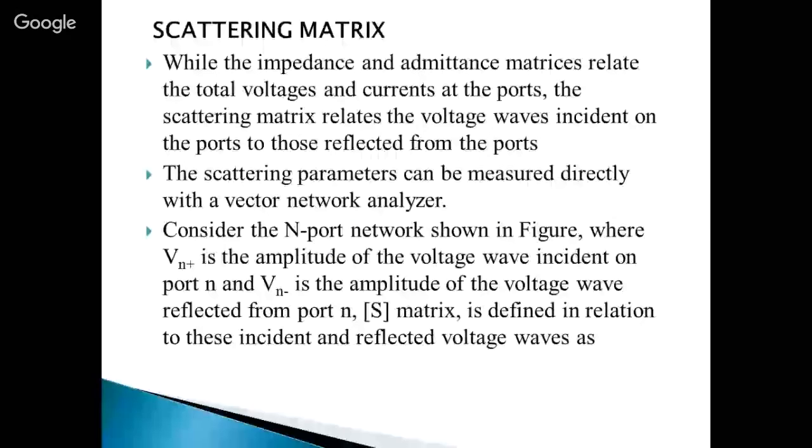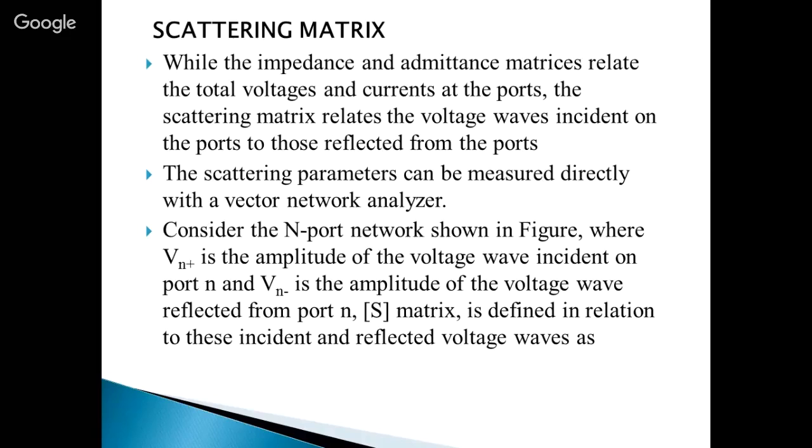Firstly, it is difficult to measure the total voltage and total current on the port of the network. Secondly, open and short circuits are difficult to achieve over a very broad band of frequencies. And at last, active devices such as power transistors and Gunn diodes at high frequency will not have stability for a short or open circuit. Therefore, we have the scattering matrix,